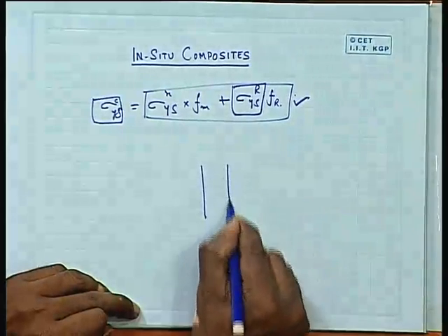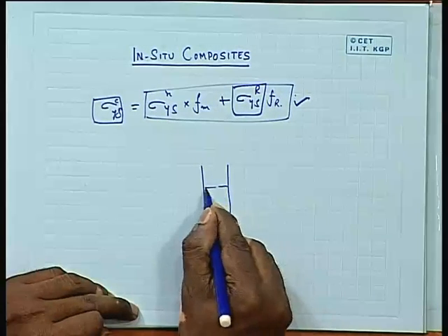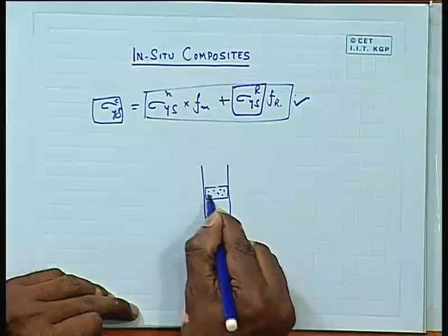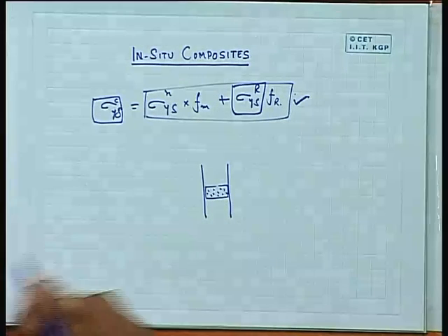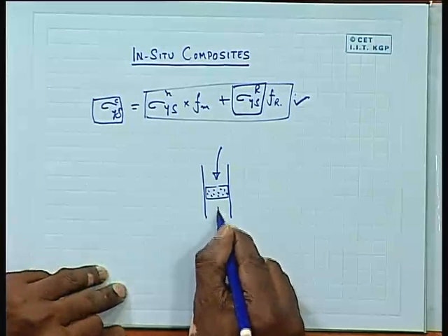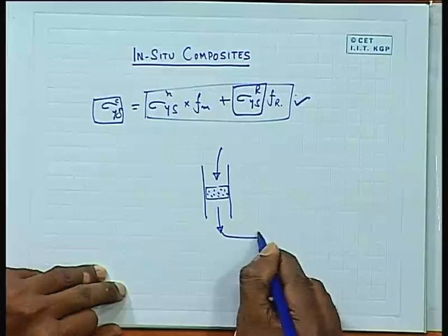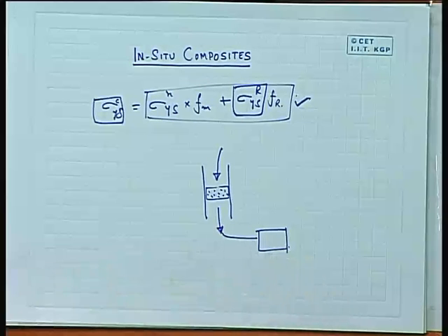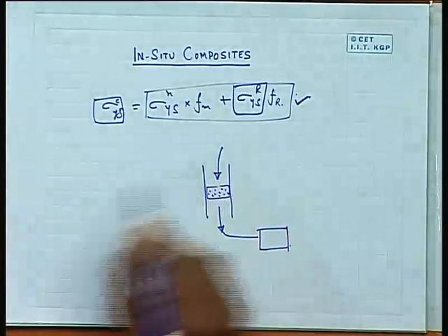Basically here what you do is you take the reinforcement particles in a tube like this in the form of a preform, all the reinforcement particles inside this, and then pour the liquid from top and try to suck this liquid through this preform using some vacuum pumps. There are different types of infiltration, pressure infiltration, pressureless infiltration. For example, if you just pour liquid metal on top of this, because of the gravity also the liquid tries to go through this so called preform, and if you have the preform basically containing these silicon carbide particles,